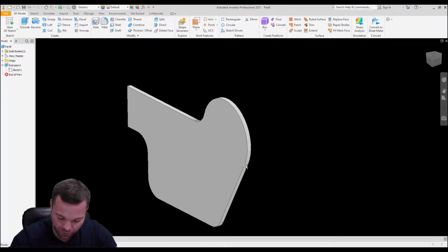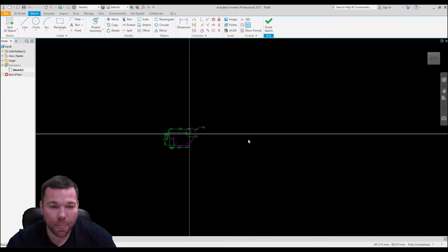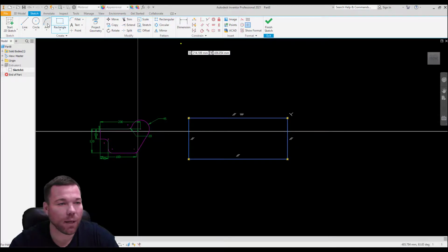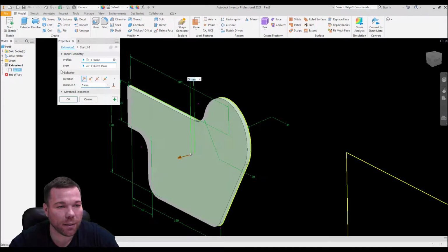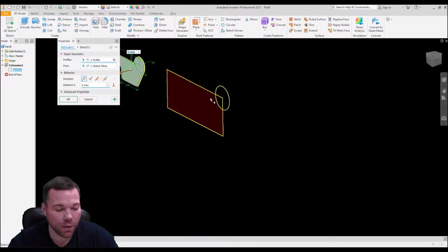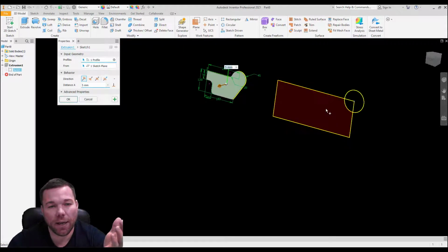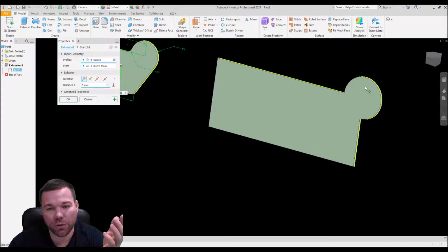All right, so I knew something didn't look quite right. All right, so we're going to edit the sketch now. Again, it has us drawing a rectangle and just adding a circle on here and hitting finish. And then we're editing this extrusion. So really all we're demonstrating here in this tutorial is just that when you extrude something, you have to pick each section of it if it's sectioned off.